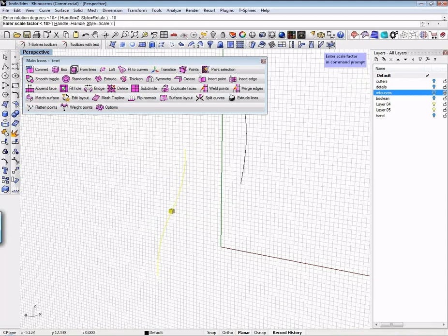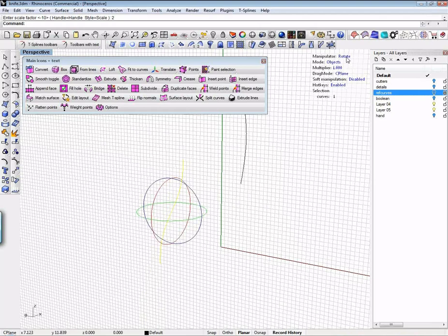If I want to double the scale, I type a factor of 2, and I can control it that way. The final manipulator is hidden, which hides the manipulators, obviously, by the name, and then I can just click through and get to those. Now, there are hotkeys for these, but for the purpose of this, I'm not going to be using any of them because I don't want you to get lost on the hotkeys.